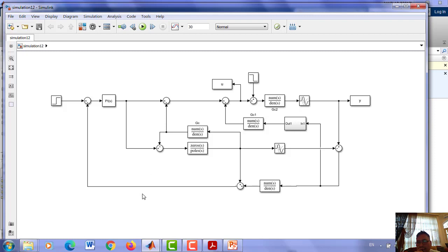What's the difference here is the proposed strategy gives satisfactory closed loop response under both the nominal and mismatch conditions. In this circuit, a 10% increase in gain and delay value and a 5% decrease in time constant. So the next step is increasing the gain by 10% and the delay value, and a 5% decrease in the time constant.